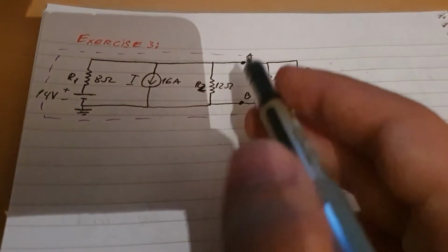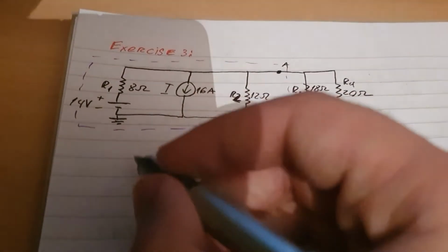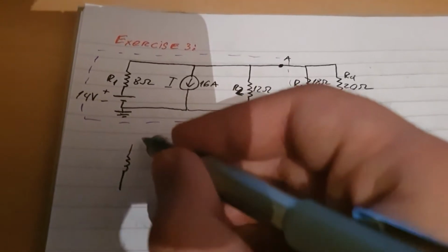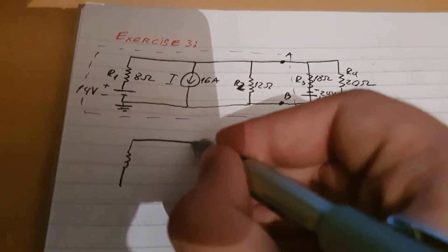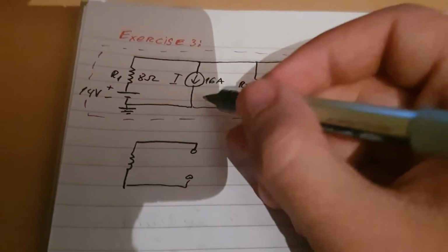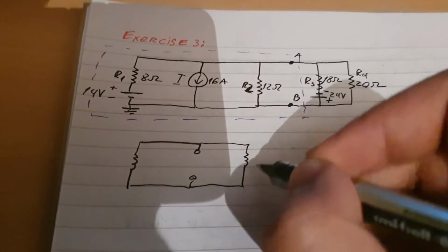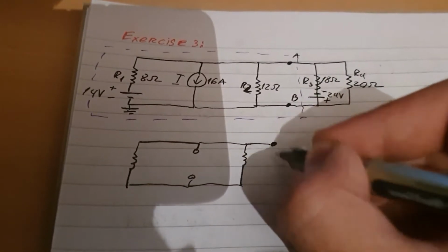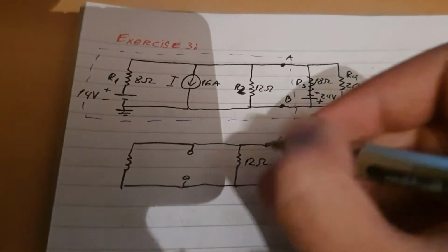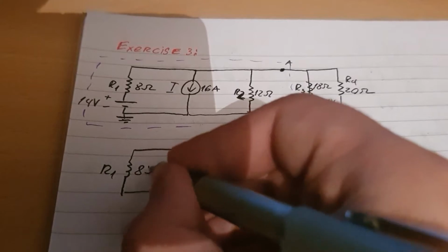First, step number 1 was to point out, and we did point out. Now step number 2 is to calculate the resistance. So we'll use R1. There will be a line because there's this voltage source. Here is the short because it's the current source here, and then another resistor here for R2, and that's it. The rest of it is point A and point B. There you go, that's 12 ohms. This one is R2, and then R1, which is 8 ohms.